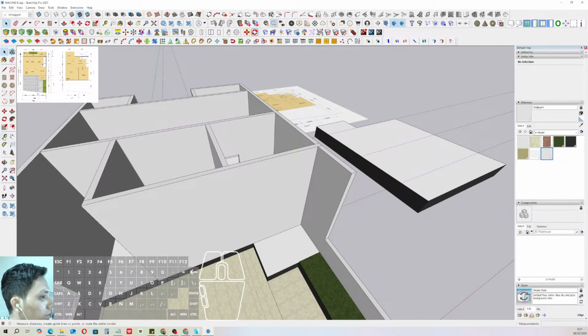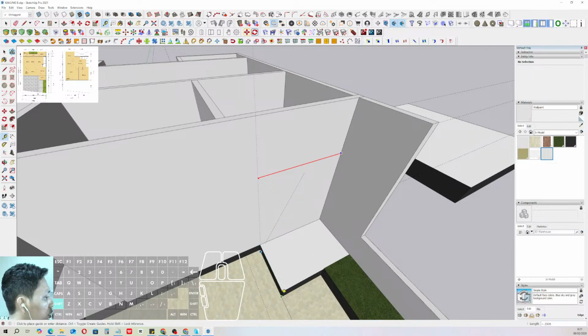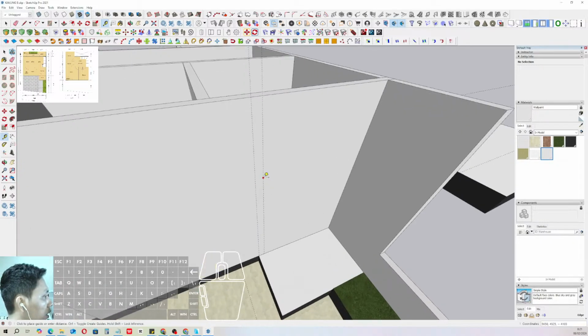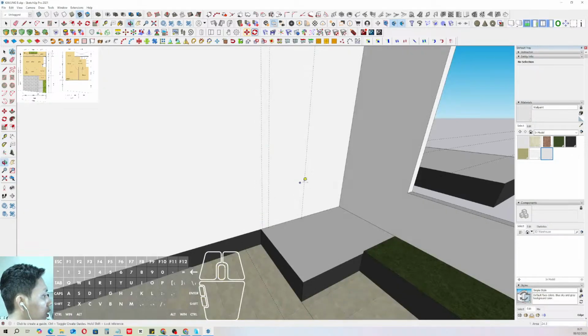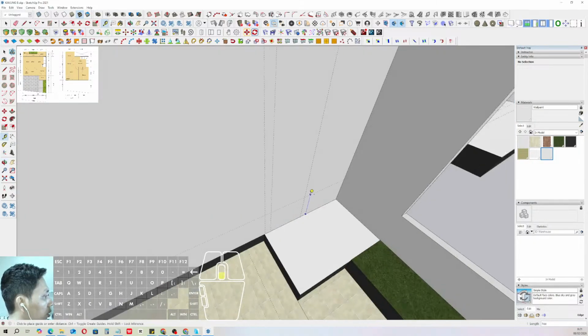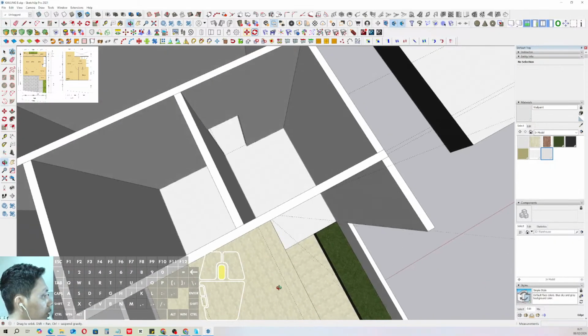We can click the tape measure tool, click from this position, and place to this position on the slab. Okay, then we can click and drag to the another side around 150 millimeter, and click again, and we can type 900 millimeter, enter. Then we can drag to the upper position for the guideline in here, 2.5 meter.